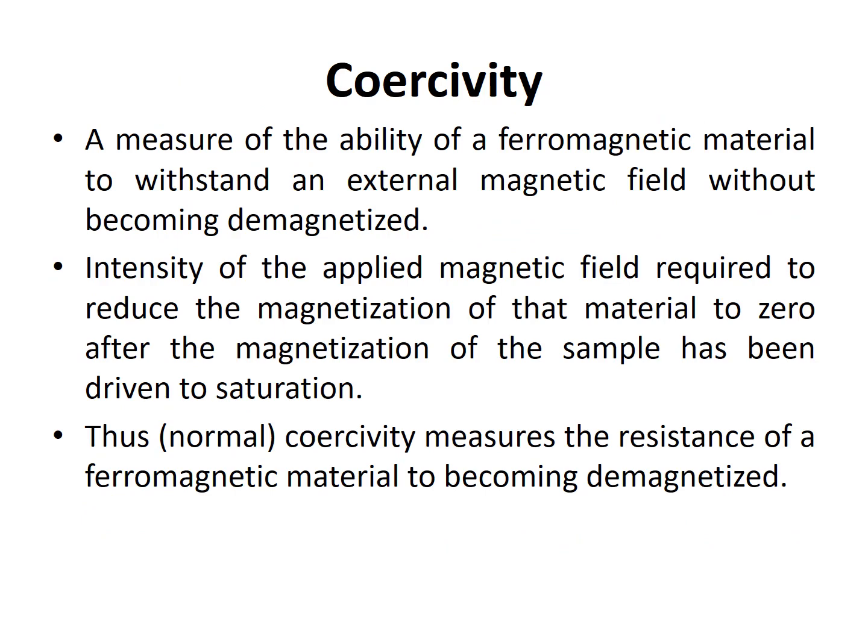Coercivity. Magnetic coercivity, coercive field or coercive force is a measure of the ability of a ferromagnetic material to withstand an external magnetic field without becoming demagnetized. Coercivity in a ferromagnetic material is the intensity of the applied magnetic field required to reduce the magnetization of the material to zero after the magnetization of the sample has been driven to saturation. Thus, coercivity measures the resistance of a ferromagnetic material to becoming demagnetized.